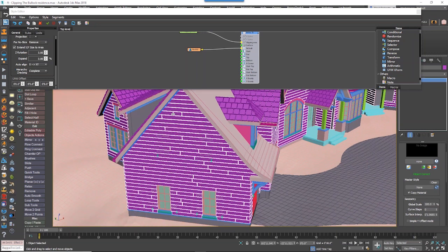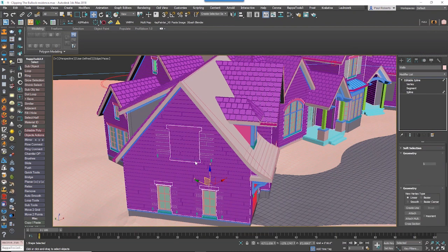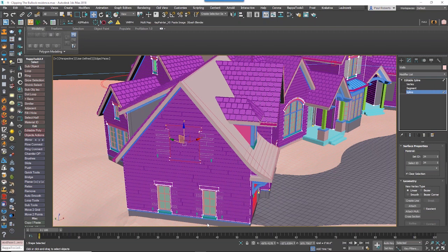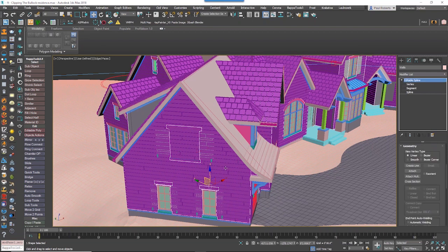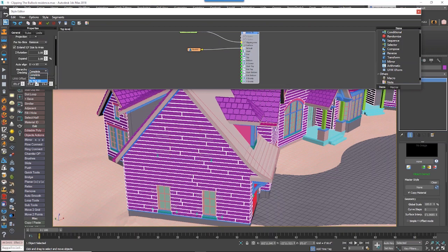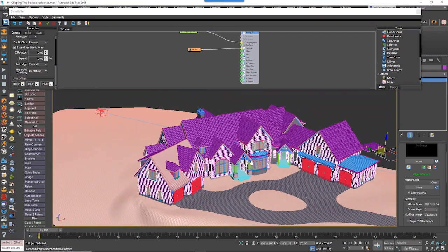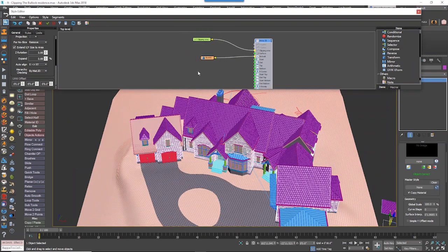You can do that by grouping together splines using material ID. So the splines that are on this geometry, if I pick the spline, have the same material ID applied on this side. You can see it's 34, and this outer one here should be 34 as well, which it is. That's a way of saying to RailClone, hey, these splines belong together, so use them as such. Then all you need to do is switch hierarchy checking mode from none to by material ID, like so. And that takes care of the whole thing. So you can really quickly populate a whole house using very simple 2D arrays to do that.